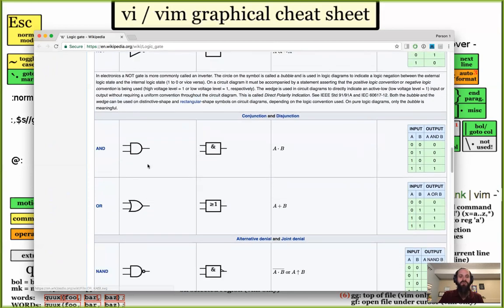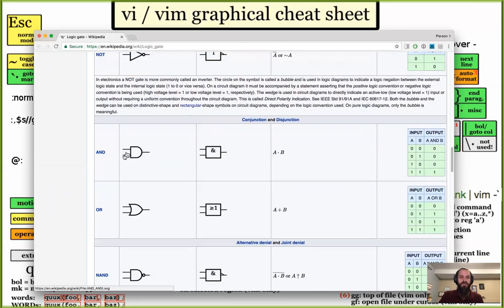And then using other combinations of transistors, you can build AND gates such that if this wire has power and this wire has power, then the output wire has power. Okay, and each one of these logic gates comes with a logic state table. So imagine that wire 1 is A and wire 2 is B. If A is 0 and B is 0, the output is 0. If A is 0 and B is 1, the output is 0 because it's an AND gate. It only works when they are both, when it is A and B. All right, so we see A and B produces 1.